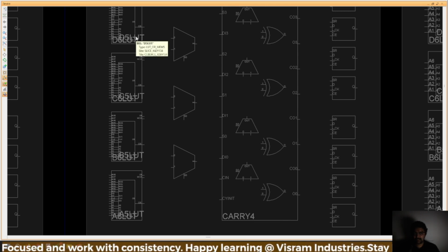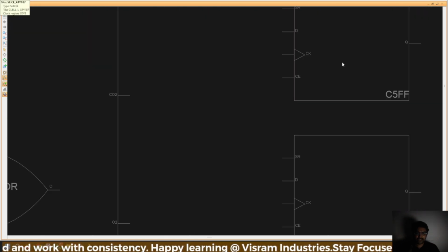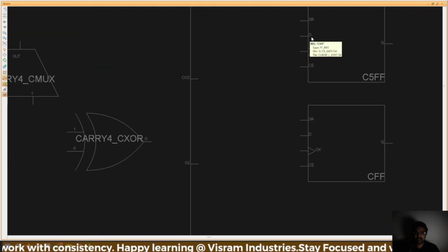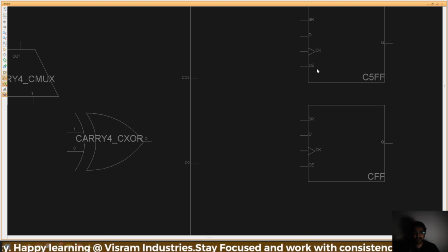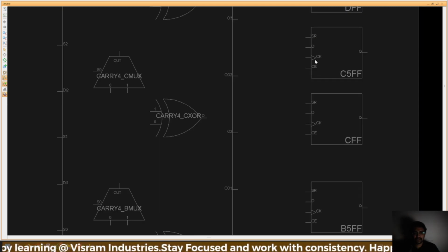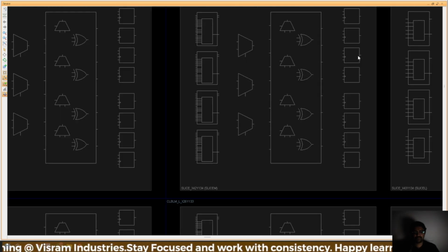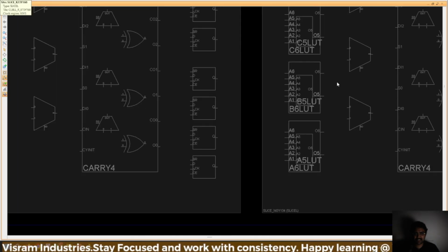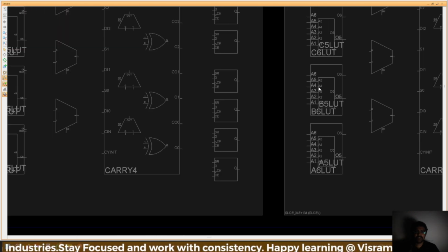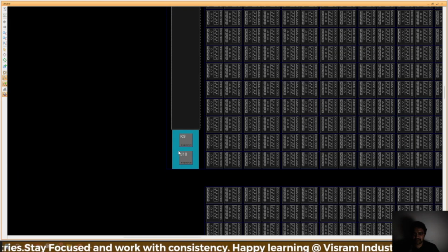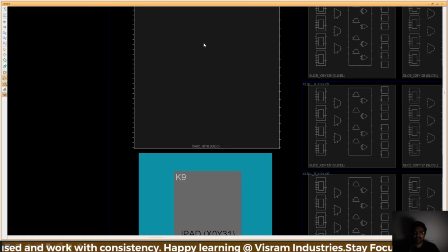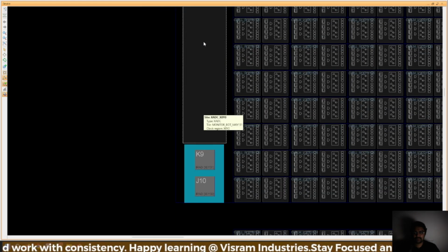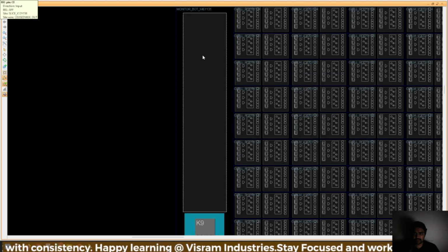LUT represents a lookup table, and see, every block or every cell has a D flip flop. And what is this called? Init, flip flop initialization and clock enable, clock output queue, all these things. That is what we are designing in the everyday sessions, the lookup tables. So some other parts, you can see the pads in the output and input pads, and this is a monitor device.